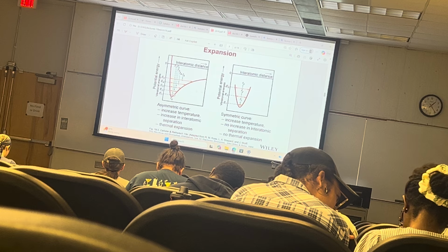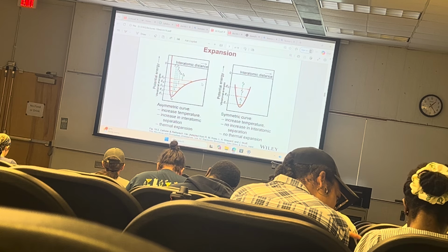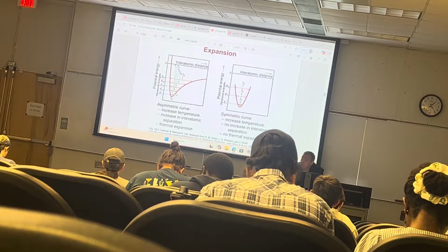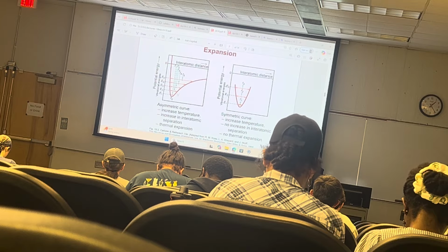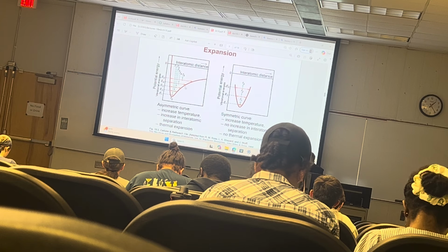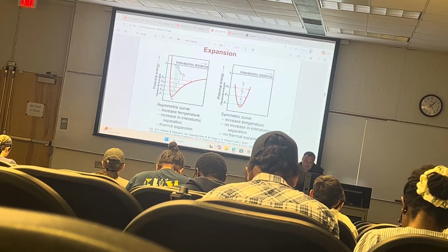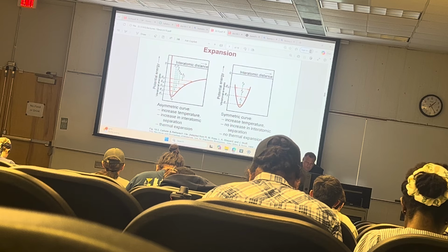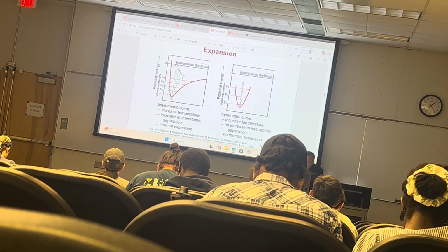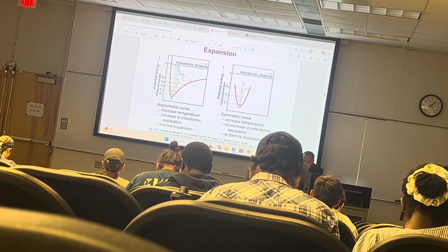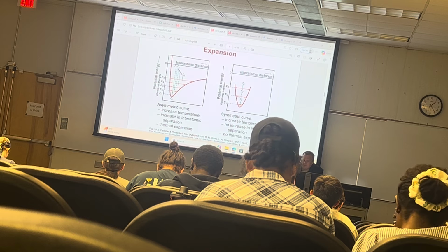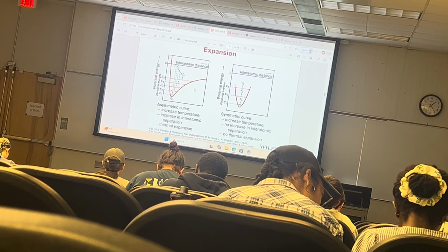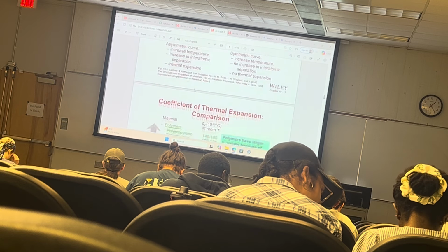Does that make any sense? So for most of the materials, the potential energy well, which you've done the homework on in the beginning of the class, it's actually asymmetric, and the equilibrium distance is increasing from R0 to R2, 3, 4, 5, and so on and so forth. Here, the position does not change. R1, R2, R3 is the same. That's because the curve is symmetric. And most of the materials are like this. They're asymmetric.